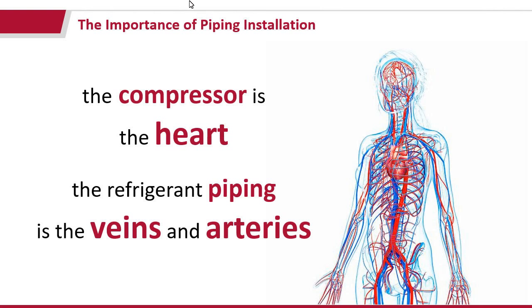But on the contractor side, if we have any contractors listening, this means be very careful with how you install the piping, as by the book as you possibly can. Keep those runs straight with the long sweeping bends and that sort of thing, not really jagged and wavy and all over the place. I've seen some interesting things out there, so everyone kind of does what they do when they get out in the field, but it really does matter.